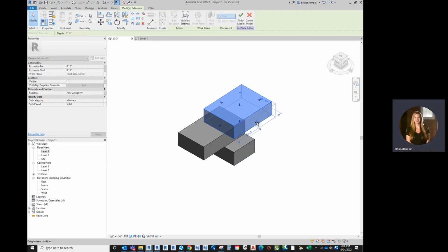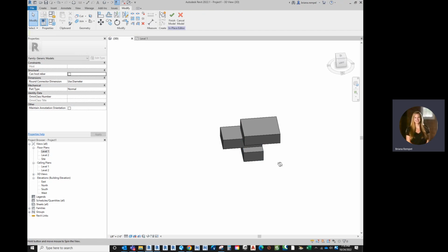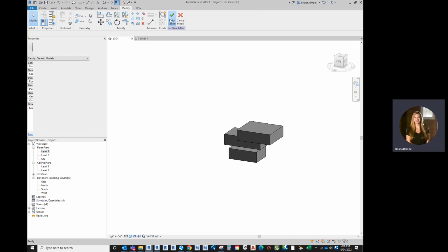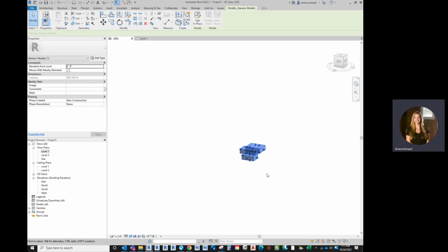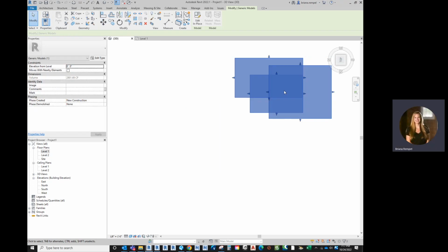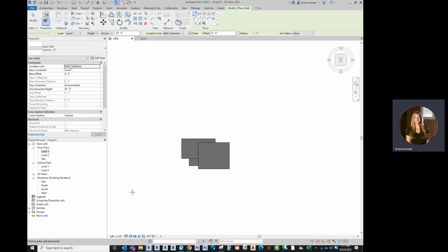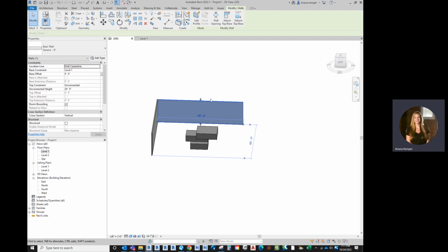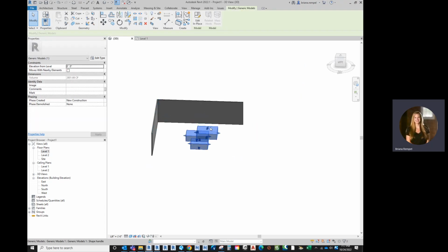They're each their own unit, or, let me phrase that: these are each their own extrusion, but right now they are all in the same model. What I mean by that is you'll notice I'm still in the model sketch mode here. Once I finish that and I hit finish model, then when I'm back in my project and out of that sketch mode, you'll see that all 3 of those are one item. If I wanted to move them, they would move together as one item. So let me put some walls in here just so you can see the distinction: the individual walls versus one component here.